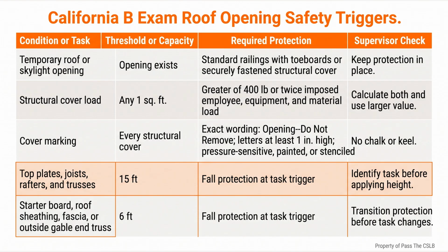Header span controls the 4-foot and 6-foot decisions. Tail joist length controls the 12-foot support decision. Distance to bearing controls the 3-foot permission. Chimney width perpendicular to slope controls the cricket rule. Roof slope controls the curb condition.